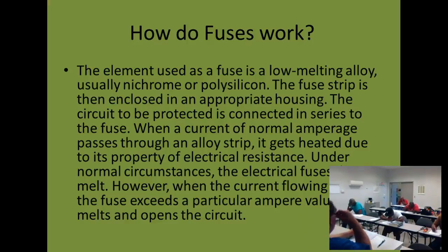So what they're saying is, when this motor starts up, let's say it's a 3-ton compressor, it's going to pull about 20 amps. We usually say about 7 amps a ton, so you need about a 20 amp in there. If it got much over that, I've got a problem with my compressor. Let's cut it off, check out my system, make sure nothing's wrong.